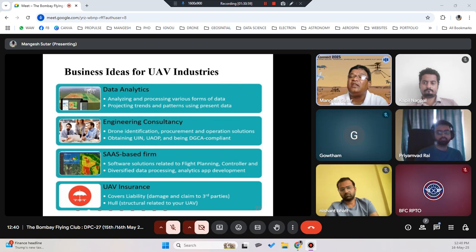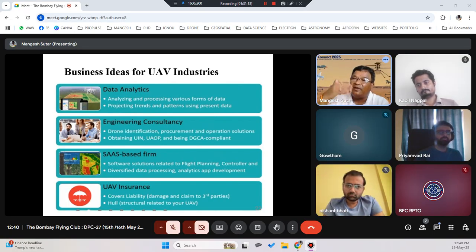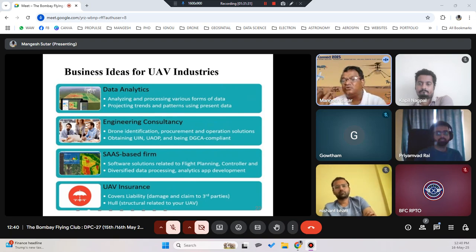The pilot was only there to bring the drone out, power it, upload the flight plan, put in the memory cards, and execute. The drone will fly around the tower, capture, and then safely land after whatever parameters are defined. At that point my pilot will only change the battery, check the memory card, and if required transfer the data, then put the battery and memory card back and fly further like that. So the workload of the pilot has reduced enormously.